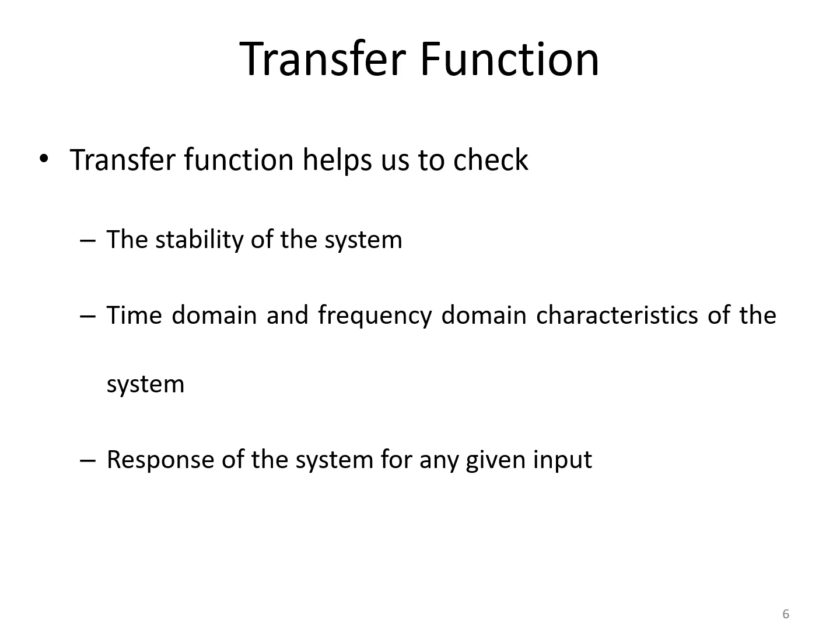Now, what is the importance of the transfer function? The transfer function for any system helps us to check, first, the stability of the system. So if you want to analyze stability, you need to know the transfer function for that particular system. Also, the transfer function helps us to find the characteristics of a system in time domain and frequency domain using suitable transformations. Another important aspect is that the output response of a system can be found out using the given input by knowing the transfer function.